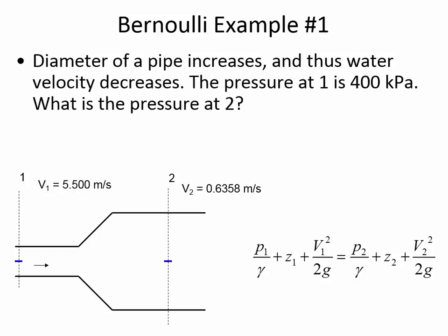And what we observed by connecting these little tubes, if you remember, those of you who had the lab yesterday: the water went high when the diameter was wide, but the little tube at the throat section of the pipe, the water didn't go as high because the velocity was decreasing. But then when it expanded again, the tube is high again. So you can actually measure with a piezometer or some other pressure measuring device the effect of the velocity change. It's physically observable.